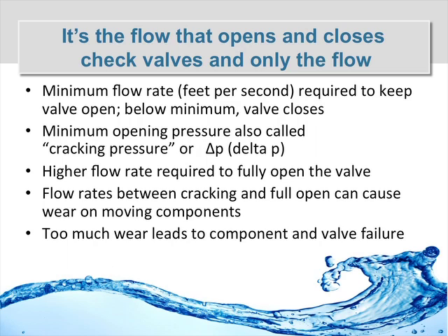But of course, we're here to talk about check valves, and the fundamental thing to remember with check valves is that it is the flow that opens and closes the valves, and only the flow. There's a minimum flow rate usually expressed in feet per second that's required to keep the valve open, and below that minimum the valve will close. Minimum opening pressure is also called cracking pressure, but what you're interested in there is the delta P, or the differential pressure through the valve during the time when media is flowing through it.